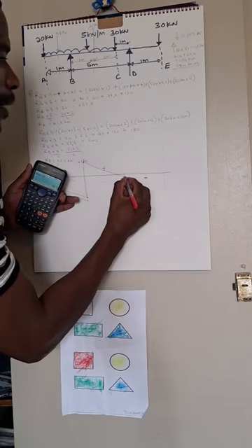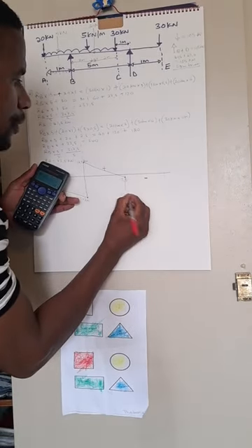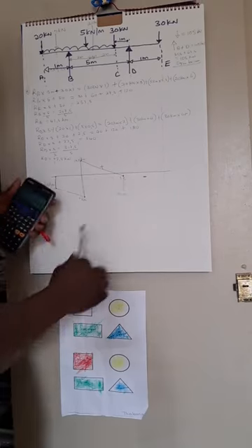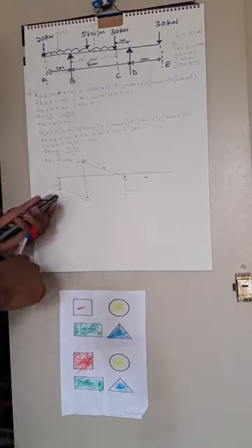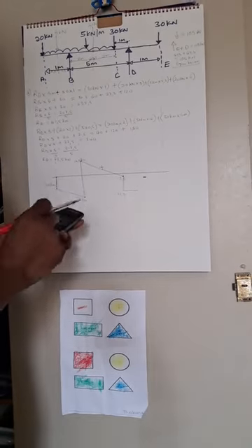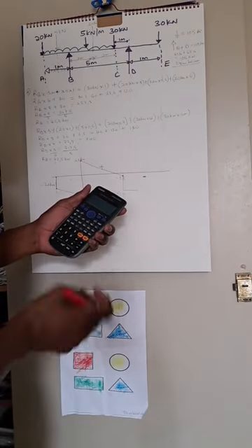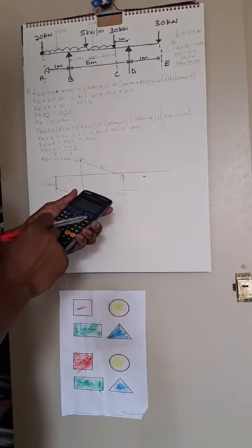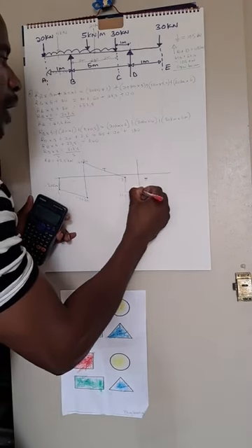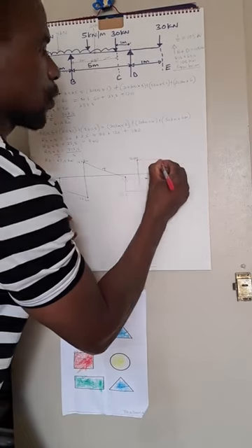So I'm getting minus 33.5. Minus 33.5. Where I am at this point, I need to join the second force. It's a straight line because CD, there's no UDL. And the force going upwards is 63.5. So, minus 33.5 plus 63.5. We are getting up to a point like here. You draw a line going upwards. I'm getting 30 kilonewtons. And then we join the last component.